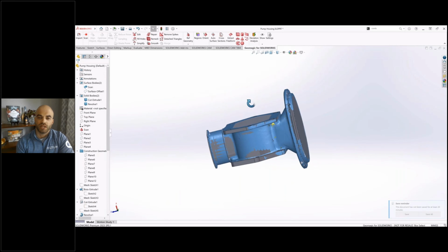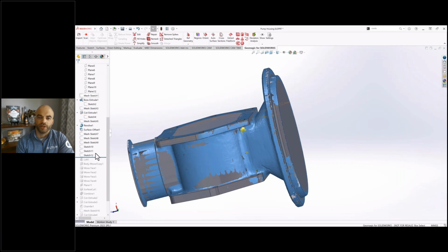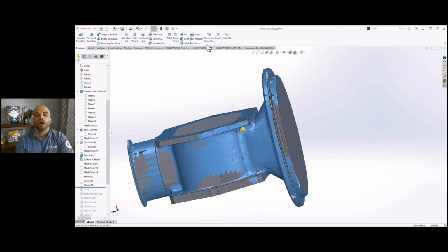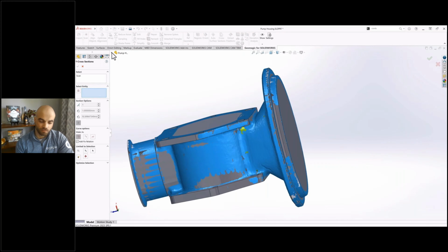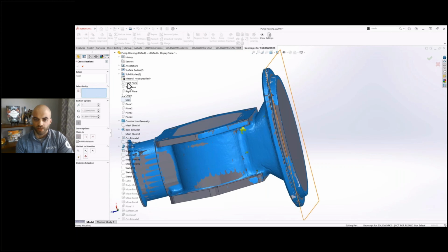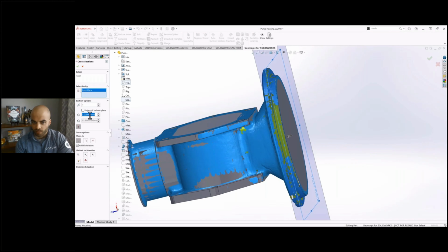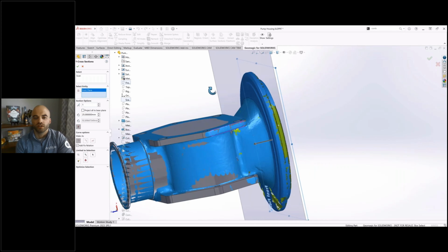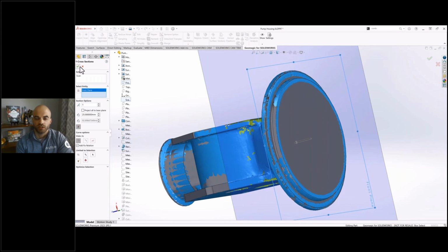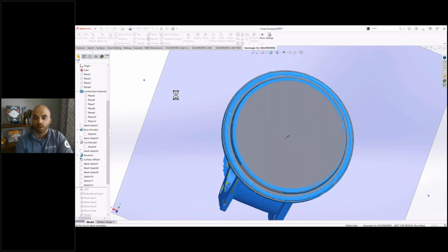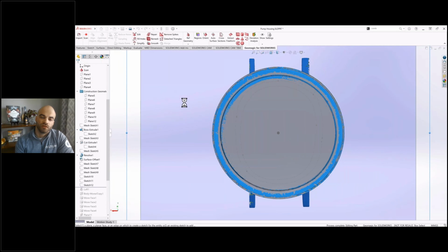And the way that I placed this, there's two ways I'll do it. I'll either do halfway in between a cross section, just as a nice clean mid-plane thing, or I'll just try to center it directly on where the deviation is the largest. And it turns out that centering this between the last profile, the circular one that was the 1 millimeter offset, and the 48 millimeter offset, so call it 25, ended up being right where it needed to be, intersecting those two large red spots there. So I got to do both of my different options at the same time there. So same process as before.